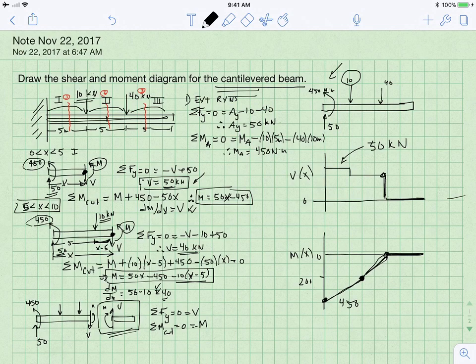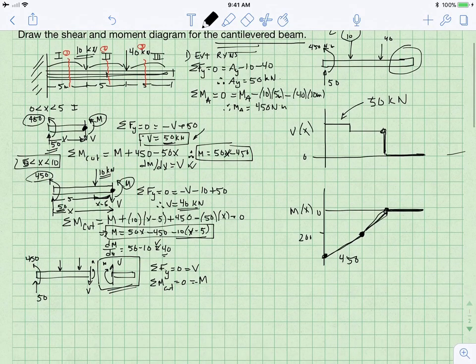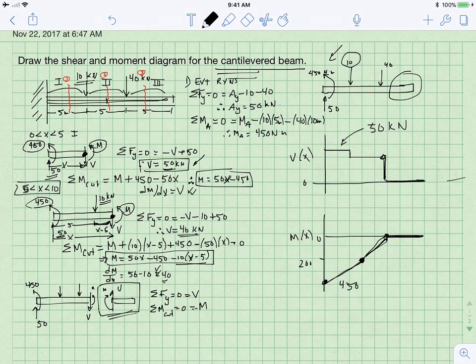Look, there's no load happening out in this region of the beam. There's no moment. There's no reaction moment needed to offset the load, and so this is the conclusion of this problem. And you might compare this to the part 1 problem that I posted earlier, because the only difference is that I've cantilevered the beam instead of supporting it at both ends. All right, that's it.